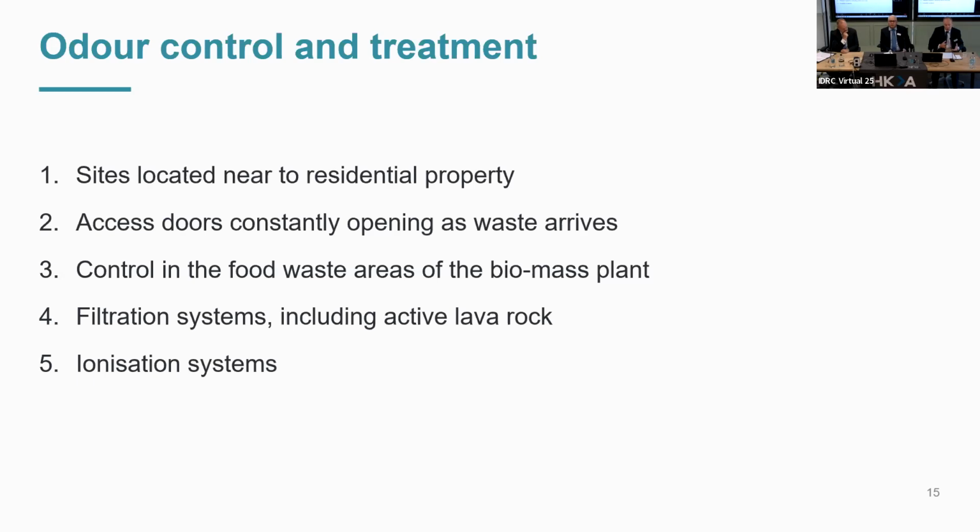On one particular project, the ventilation system was designed in conjunction with the gasification unit. So shall we say, the bad air from the food processing plant was taken and put into the gasifier and burnt as oxygen within that process. But then the client said, well, what happens if that's not operating? What are you going to do, etc. So we ended up with long discussions about how we resolve the issue.